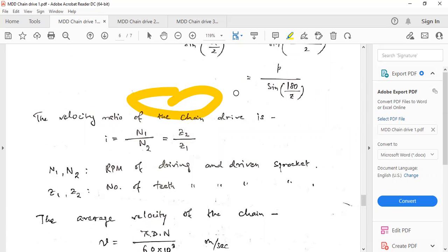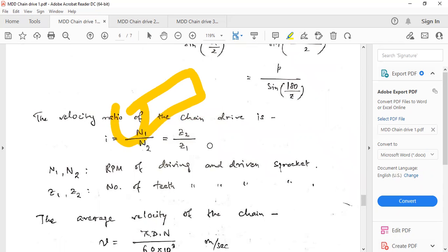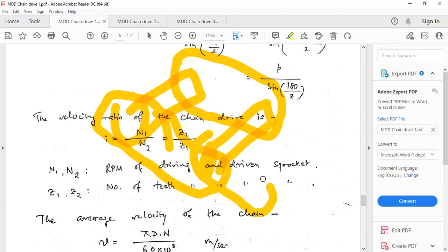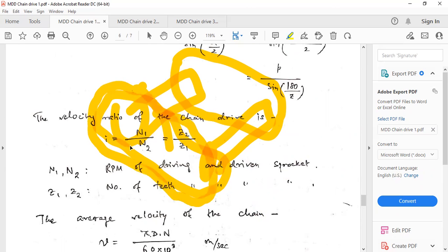Let me show it like this. One roller has another roller here. So we have two links connecting these two rollers, and one extra link has to be connected. Will it connect in this manner? No, we won't connect it, because the other side will remain open. So where to put that extra link? We will put it with the existing link only, just overlapping it.